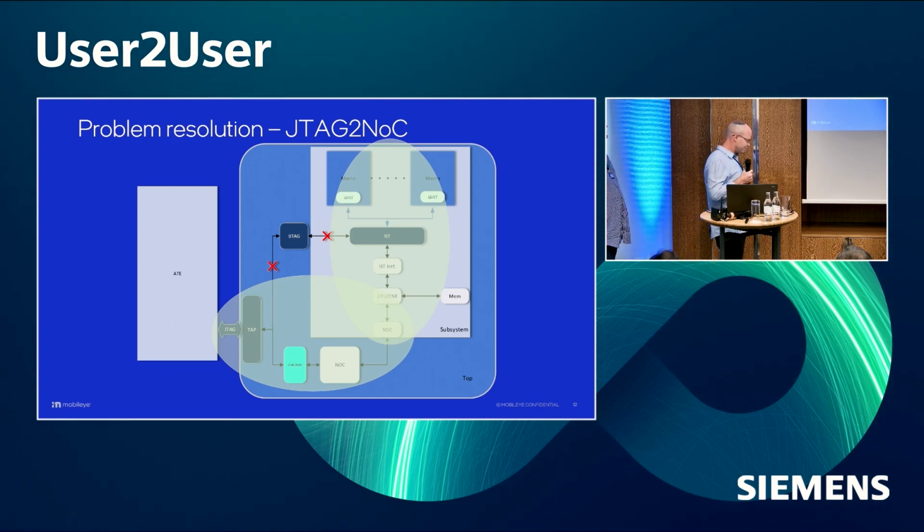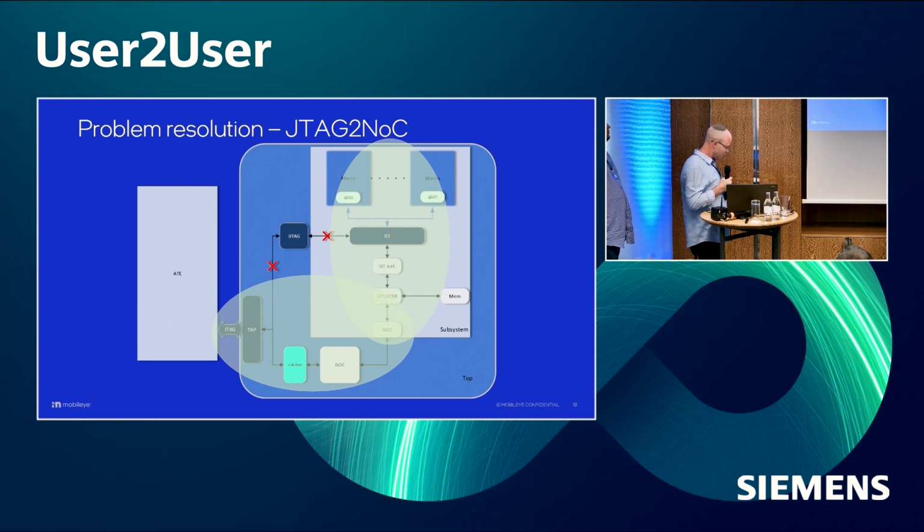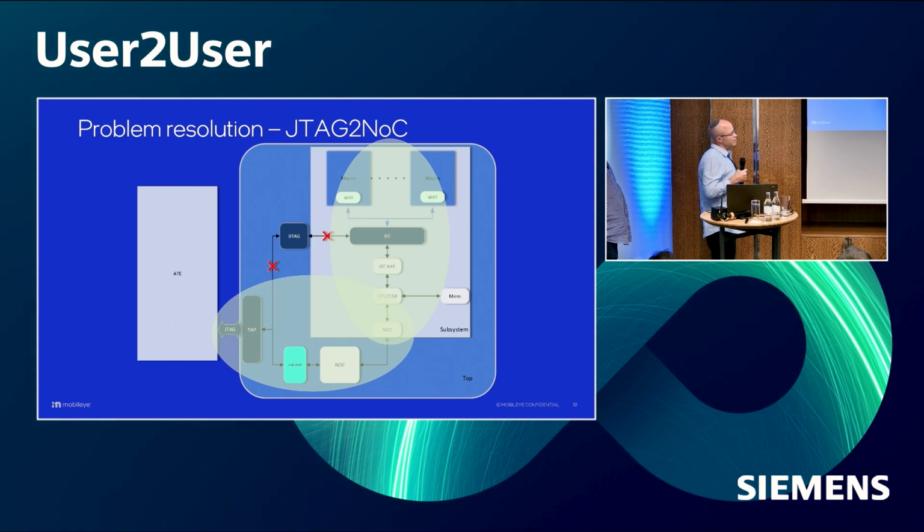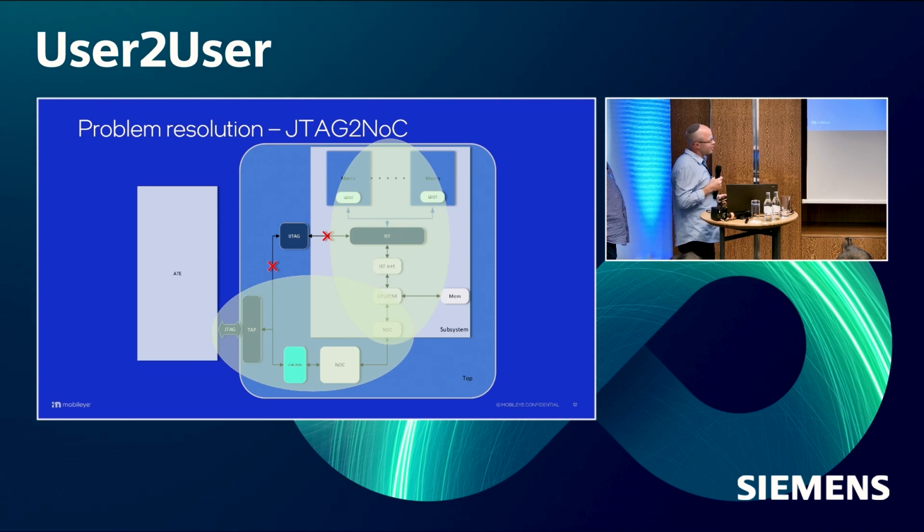Okay, so in our design, as mentioned, all of our design is actually interconnected by this NOC controller. This NOC controller can provide access to mostly all of the registers in our design. As such, if I can program my NOC controller, I can use it to program the CPU.